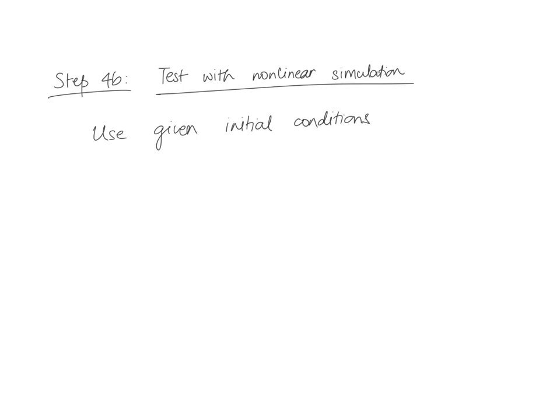And the feedback control input now takes the form, it's the PD form, and the only trick here is to write the correct PD form in the time domain. I've shown you as Kp plus Kd times s, and all you have to do now is in the simulation make sure you have u of t equals Kp multiplied by theta reference minus the actual theta. Okay, and I'll talk to you about what theta reference is.